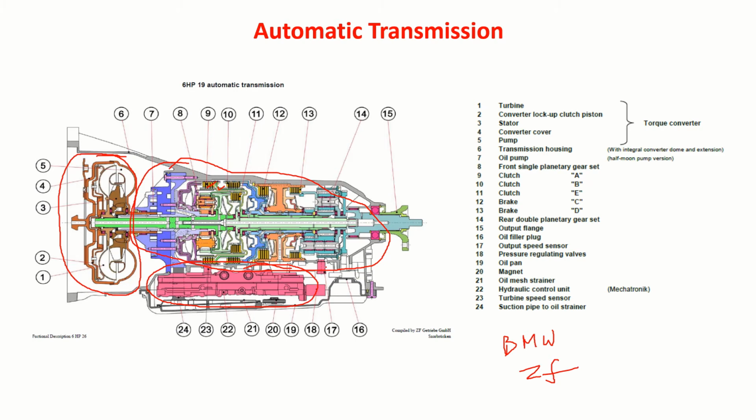Correct? This hydraulic system will give the required power to the brake to apply those clutches, and it is possible to decide which one to hold, which one to release, and all those kinds of things, and it is possible to get different combinations. So based on the control logic, the hydraulic fluid will be made to flow to the various brakes, and these brakes in turn will operate those clutches. This is the complete system.